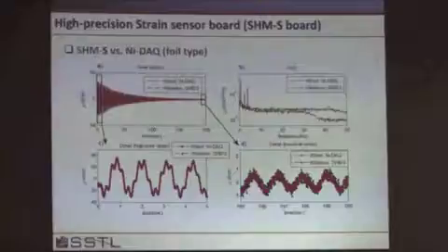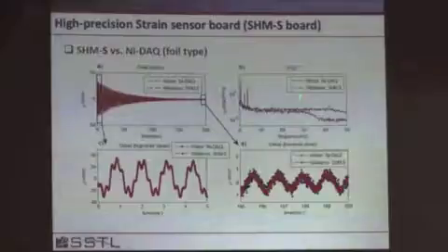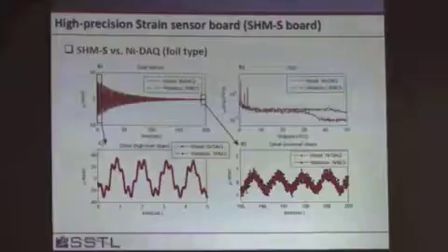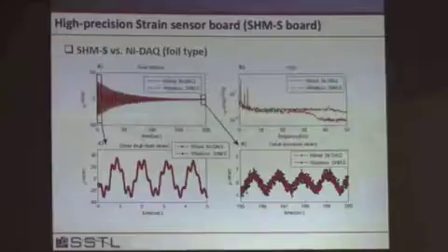How is that? Well, if you look, the wireless sensor had a lower cutoff frequency. It had a 30 hertz cutoff frequency, whereas the wired sensor had a slower roll-off. So it's the difference between these two curves at this higher frequency that results in this additional noise that's seen in the signal.